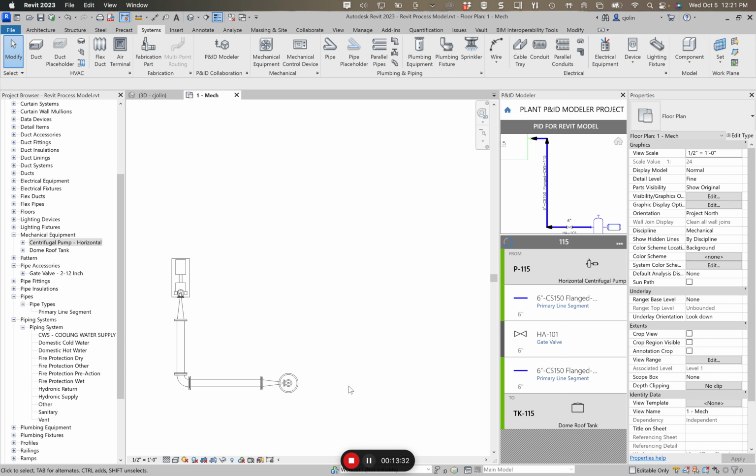Okay. You'll see something interesting here. It made the connection, but it changed the diameter of the pipe. Right? So even though I had that ability from the pipe routing in Revit, I could start at the connection point on the tank. I could transition immediately to a 6-inch diameter, and it would put a fitting in at the connector on the tank.